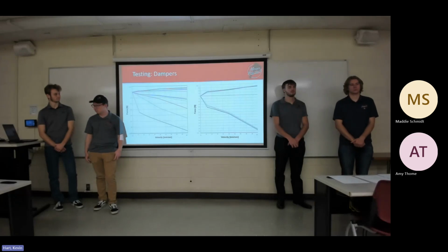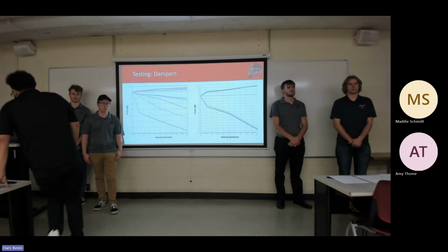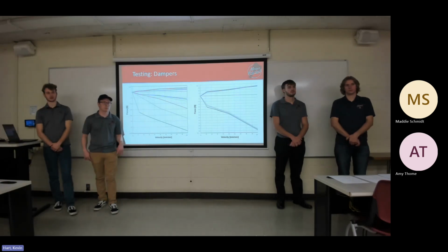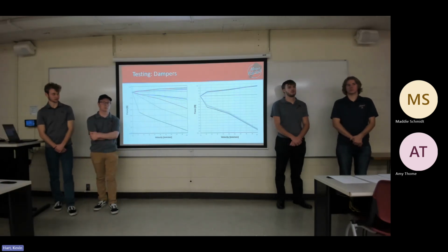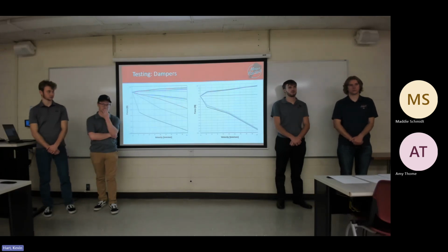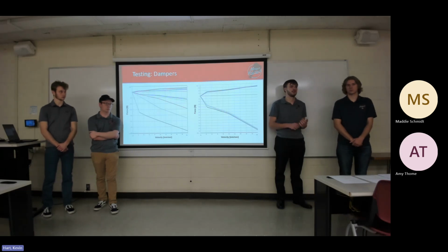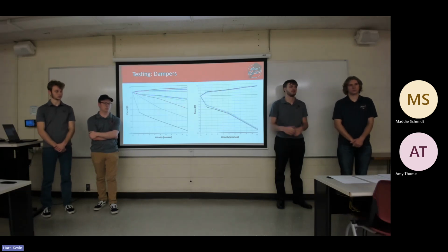This is the last question. I'll say good analysis, good testing, everything. Have you done any response analysis, any dynamic response analysis on the dampers themselves? We have not currently. We know what our target damping ratio and compression and rebound are going to be, and then once we are able to pin down our spring rates off of the simulation and our target roll rating and ride frequency, we will go from there in terms of transient response. As a plan maybe for next. Yes. All right. Sounds good.